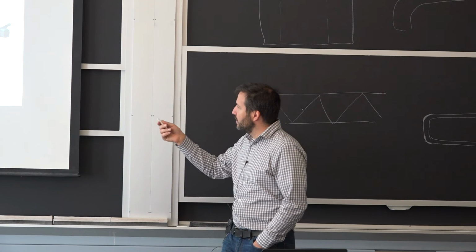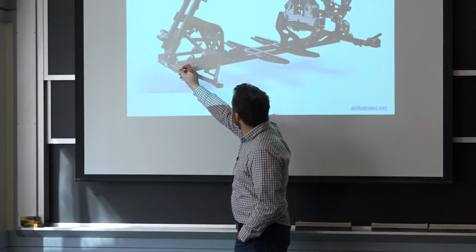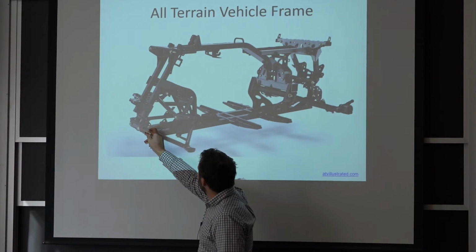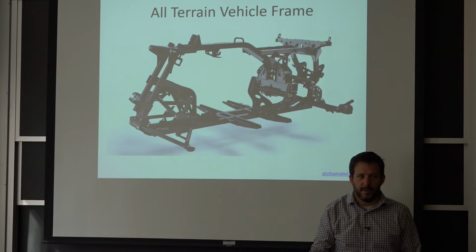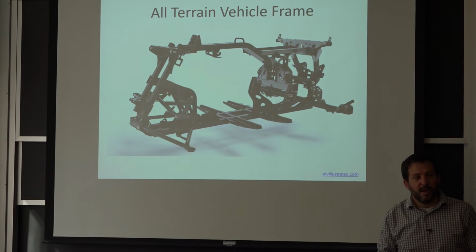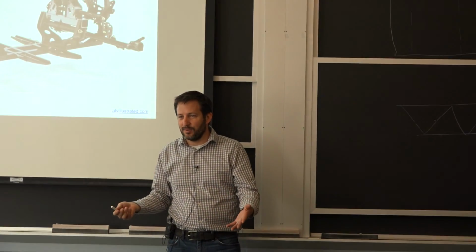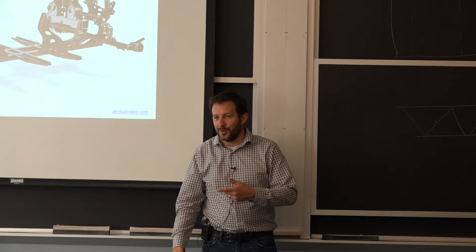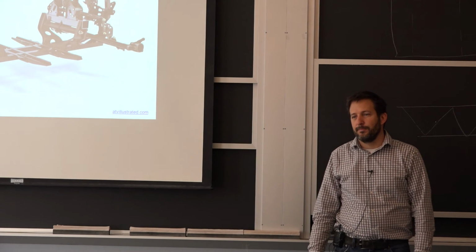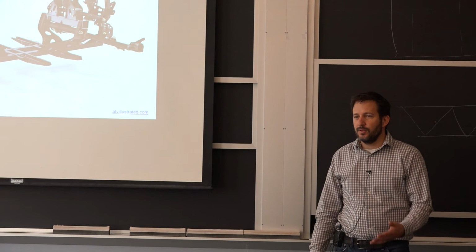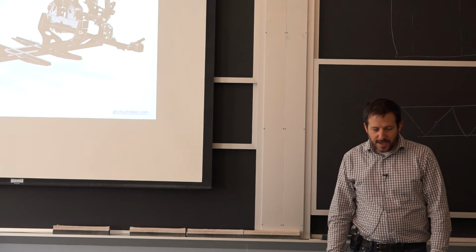I would say that the biggest consequence of a monolithic frame like that that I have seen, and it does have some extra components, so here it is bolted for the arm, but let's say the frame here gets bent because you overloaded it, you ran into something. A lot of times there's no real way to fix that damage because it's just an entire frame. So you have to replace the entire frame and remove everything else out of the unit if you damage the frame. And the main reason is there is no good way for you to get the right dimensional stability. So it's not as flexible.